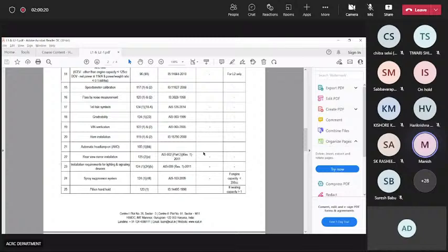And then point number 24 is spray suppression. This basically talks about your mud guard and huggers. There is a definition for mud guard and huggers, how much cover it should provide to the rear wheel, so that the person driving behind you doesn't get water splash or mud splash. So that definition comes under spray suppression. That is also part of the homologation.